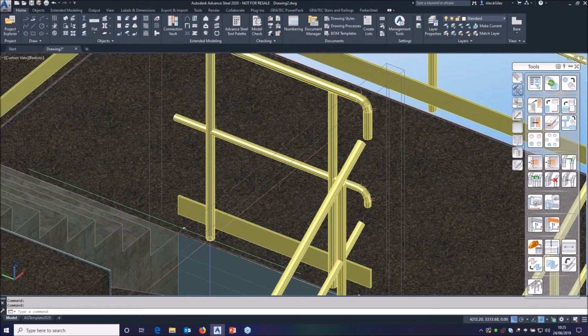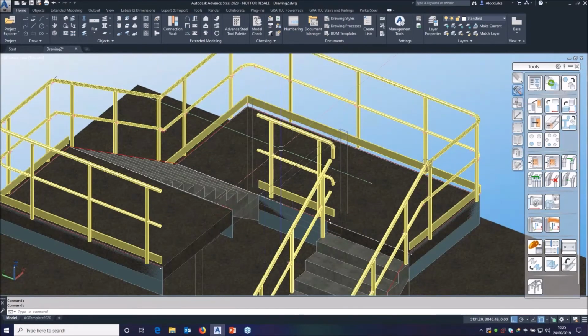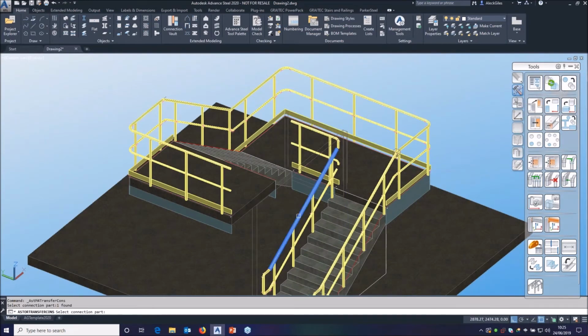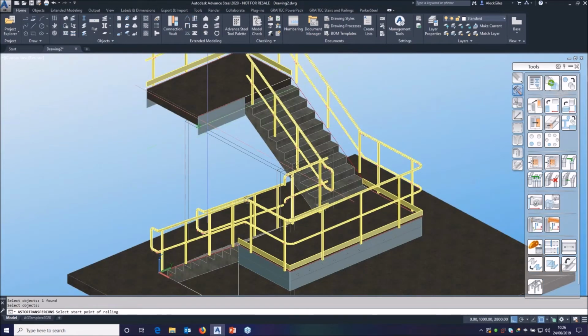Again, I'll leave the connections on the post connection because that's going to come later. There's nothing in the joint. It's assuming it's for steel beams, so it's using bolts. We need to use anchors into concrete. Okay, so I can do a joint copy on those two again. So joint copy that one for the stair, and joint copy the landing one onto this beam. Like so. And again, they're obviously going to need small adjustments.